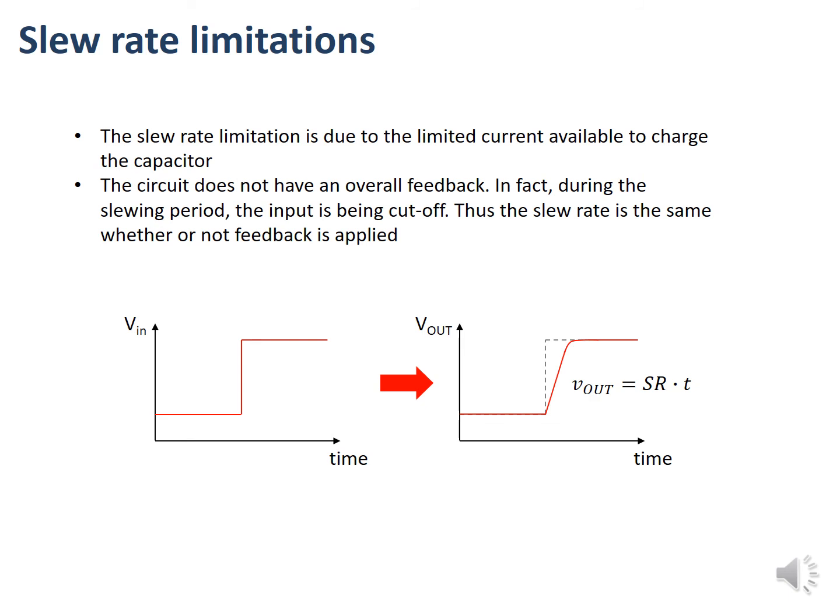So this causes this lack of response, where we see the square wave become a little bit more like a triangle wave on that corner, as shown in this diagram. This is regardless of the feedback loop that I may have in the circuit. So it's nothing to do with the feedback network that I have in the op-amp circuit, in most cases. It's just an inherent problem inside the op-amp, and it's the same whether you connect that feedback or not.